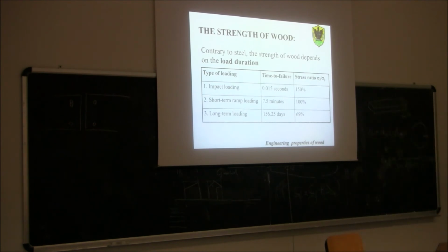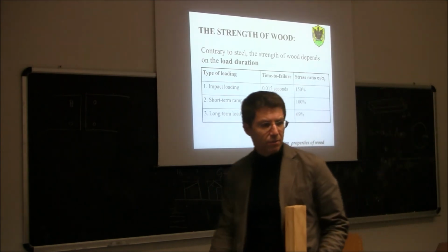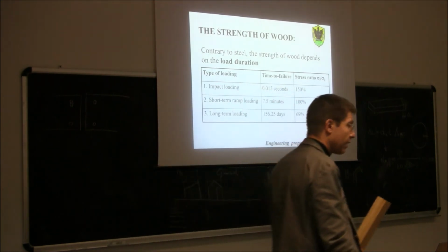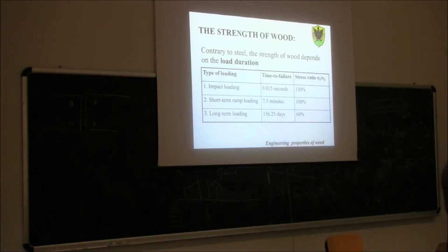Now, suppose we go the other way around. Rather than applying this load in 7.5 minutes, we apply the same load in 1 year. So we increase the load very slowly, in order to get the value after 1 year, or after half a year, so 6 months. Would we get the same strength? No, we will get less strength in the same specimen we're talking about. We get 30% less. So this is evidence that for the wood material, the strength depends on the loading rate.